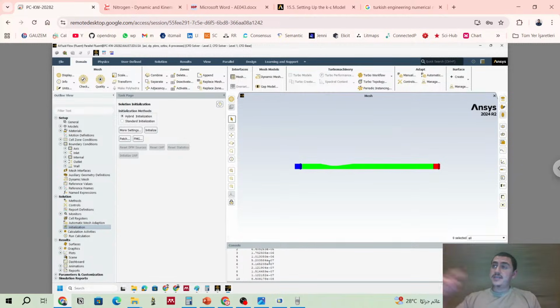Then at each iteration step, we evaluate: are we converging? Are we getting better, lower error or bigger error? So now you see we are going to lower values, 10 to the minus 8. At the initialization, sometimes you have divergence in the first 10 steps. So you have something unphysical, something very bad, if it's diverging at the first steps. If it's going well, you are okay.